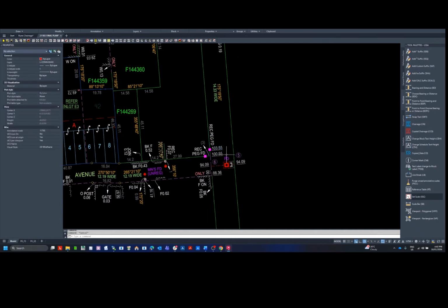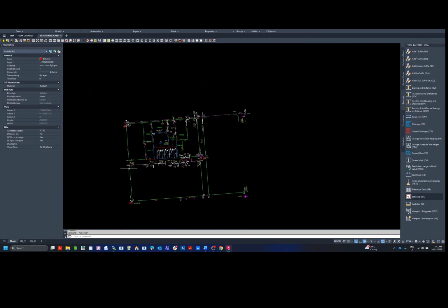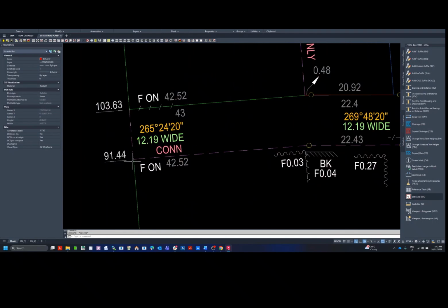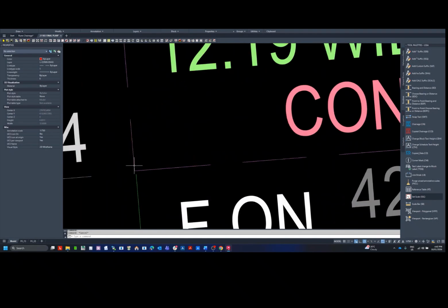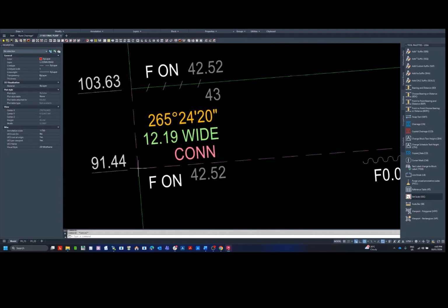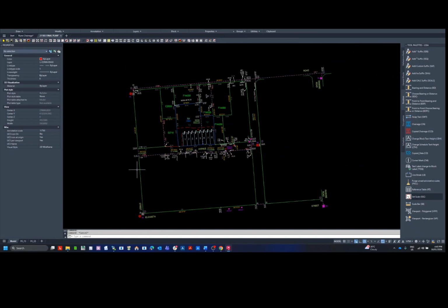Another important factor is to check that abuttal lines are snapped to connection lines and parcel boundaries along chainage runs. We do find that sometimes the extract files are used, and this can cause a slight mismatch between a connection line and an abuttal line. And any break within the line could be enough to cause this chainage run to not be able to be validated along the full run.